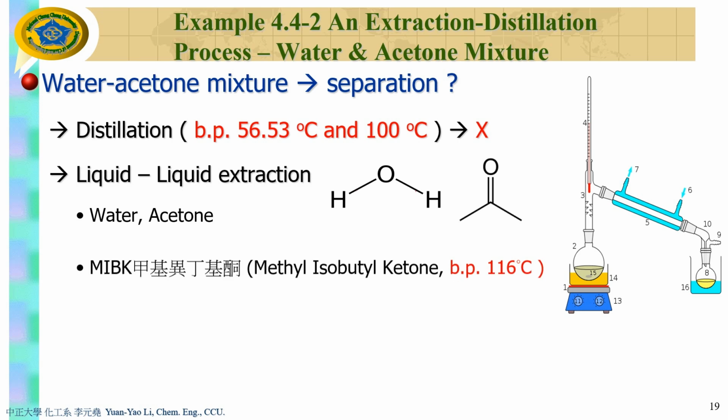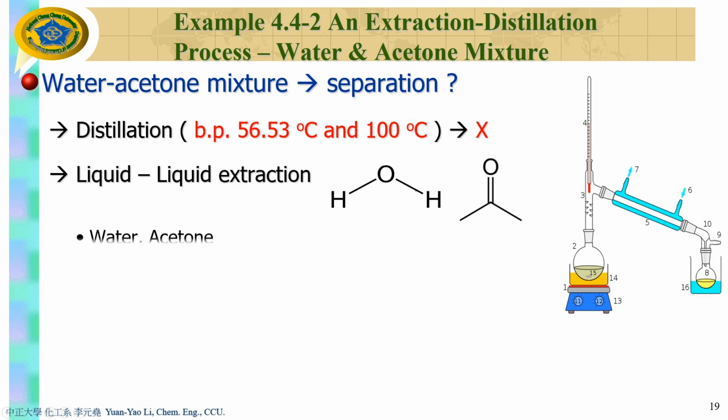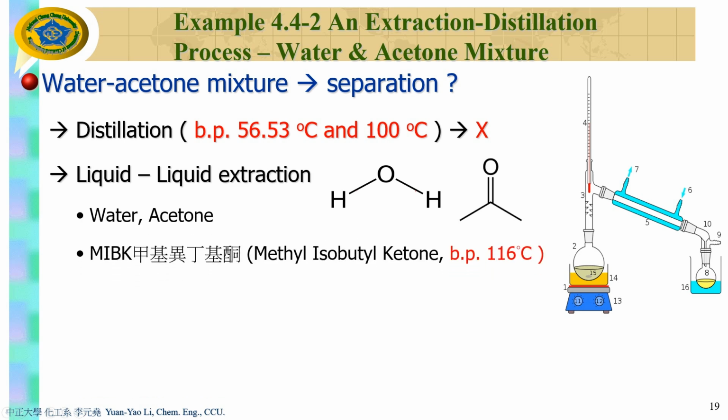Remember? These two can mix very well in any proportion, but in order to separate them, you cannot use distillation directly. You have to use MIBK to do the liquid-liquid extraction first.